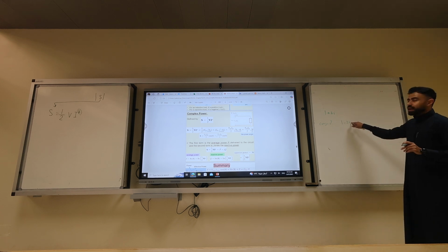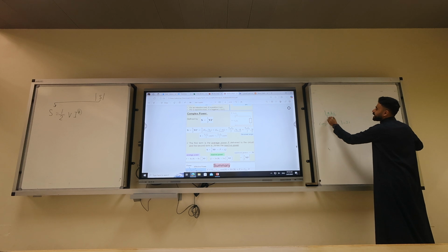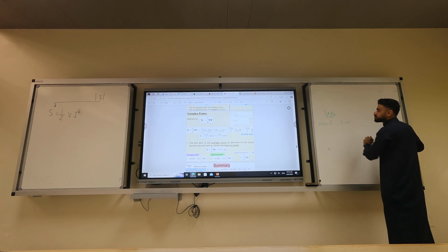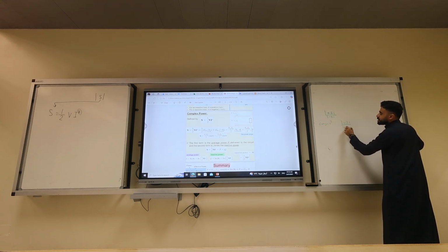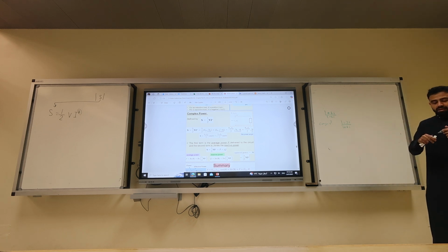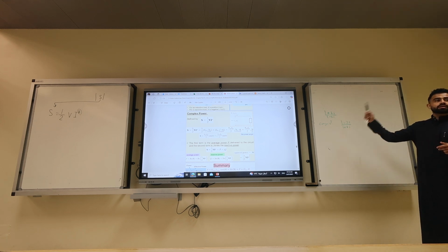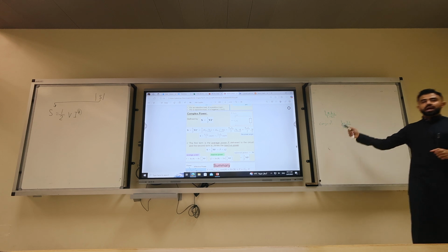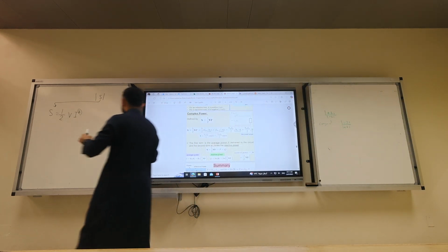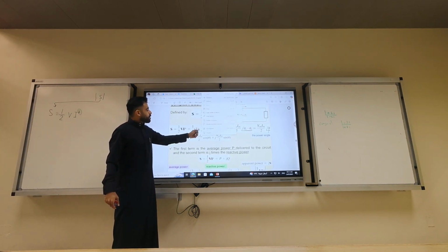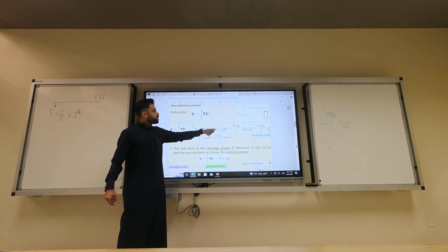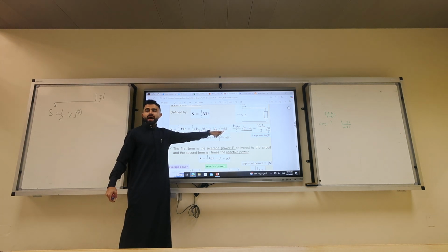So the same concept is applied here. What if I have divide by 1 minus 2j? What's the conjugate? You take the conjugate of the numerator and then the conjugate of the denominator. So what's the trick? Whenever you see a j, you change its sign. You change the sign of every j. So that's the only thing: you change the angle. And we can see it here, half Vm angle theta_V, we keep the angle, but with the current, we change the angle of the current. So that's how the conjugate is applied.